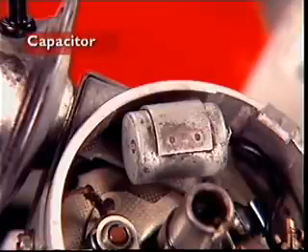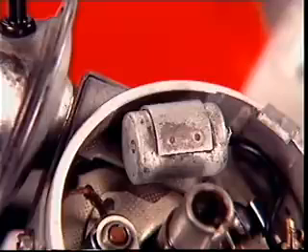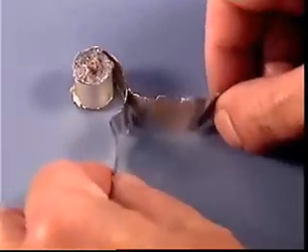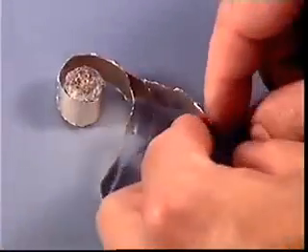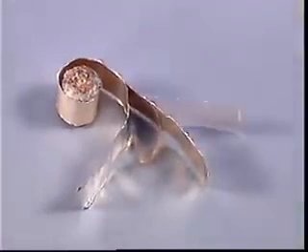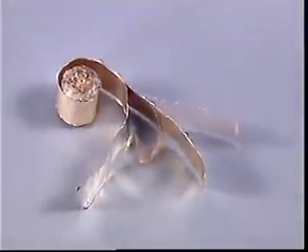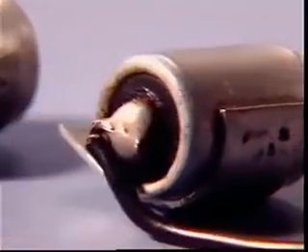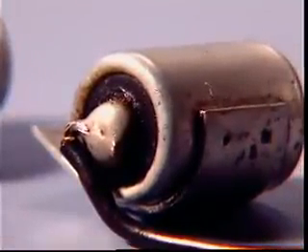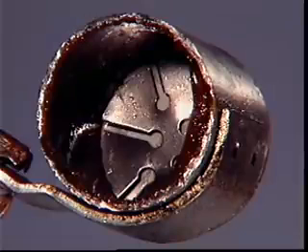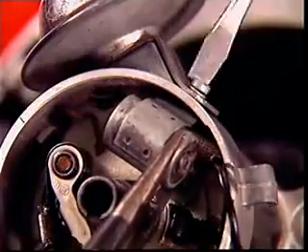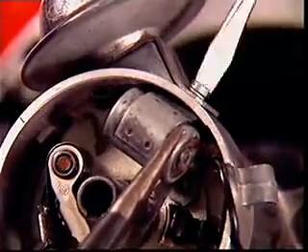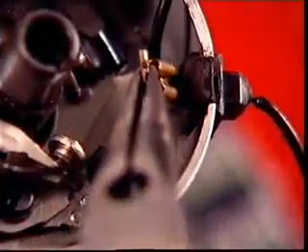The capacitor, also called a condenser, is a self-contained unit which is connected electrically in parallel with the contact breaker. It is made up of two plates, constructed from narrow strips of aluminium foil, which are insulated from each other by a special waxed paper called a dielectric. The plates and insulating paper are rolled up tightly together and sealed in a metal can by crimping the end over onto a gasket. A spring in the base forces the plates and insulation against the gasket to keep out moisture. One plate is connected to the capacitor case and through its retaining screw to ground. The other plate is connected to the external connecting lead.